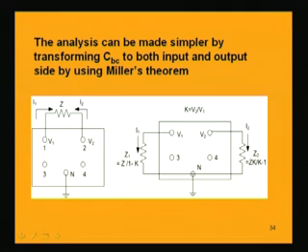How we are getting the value of the resistance between 1 and ground being Z by 1 minus k and the other being Zk by k minus 1, that can be verified if we consider the currents in both the cases and make them equal. You see the currents are still I1 flowing from V1 to ground, I2 flowing from V2 to ground, and earlier this was the current I1 from V1 to V2.